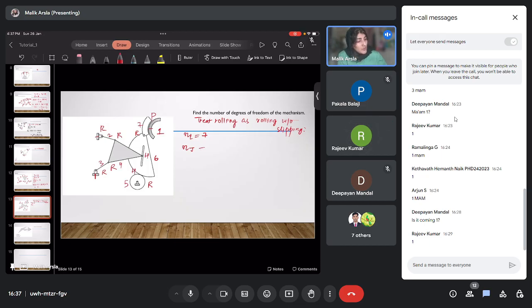So that you people understand. Now what is the number of joints? 1, 2, 3, 4, 5, 6, there are 6: 2 H and 1 P. How much is it? Then if we consider H as a single joint, it will be 9, otherwise 10. Consider it as single, because the formula we are using will take care of it. I'll tell you how. So the number of joints is 9.